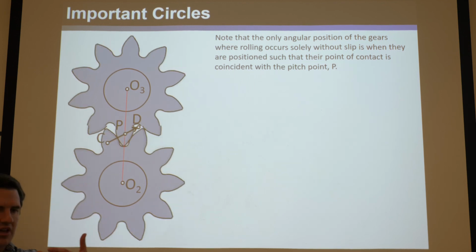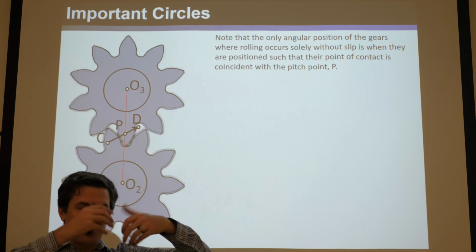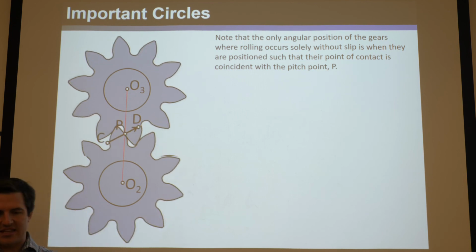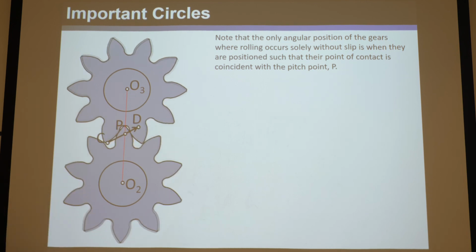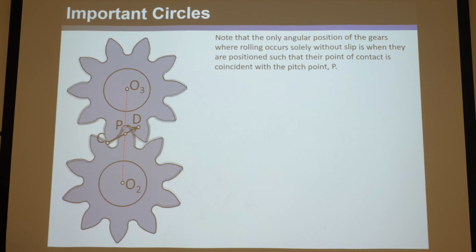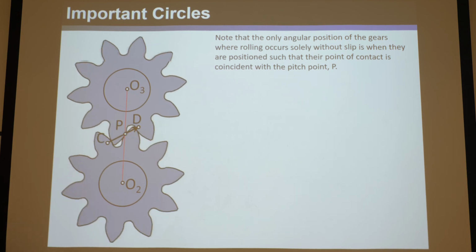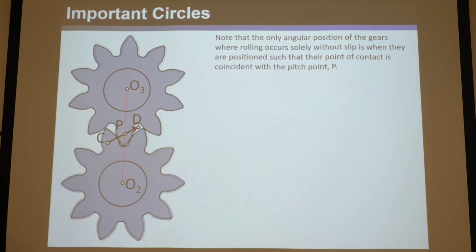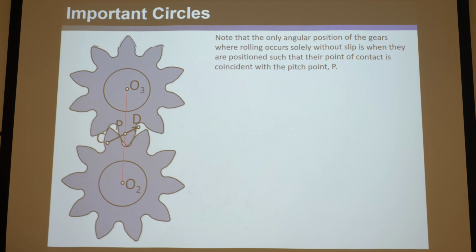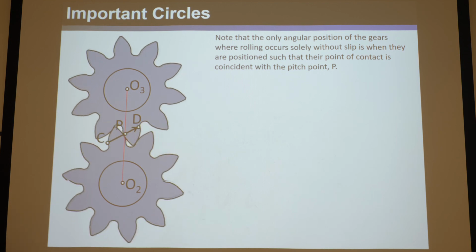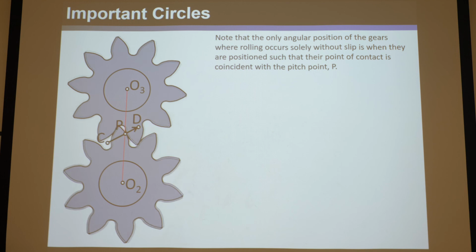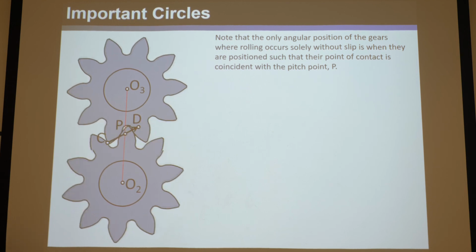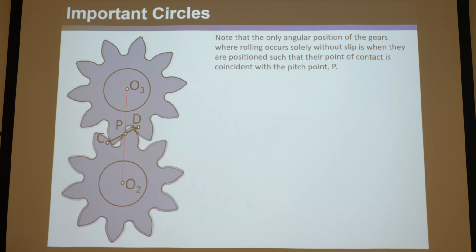That's obviously true, because if you have two gears and you shear them, if you allow the two circles to slide past each other with different velocities in the tangential direction, it can't do that because the teeth would shear off. So obviously two mating gears are assumed to be rolling contact only. By the way, that means they're a single degree of freedom joint. That means they would be a J1 joint, because they're rolling only. If it was rolling and sliding, it would be a J2 joint.